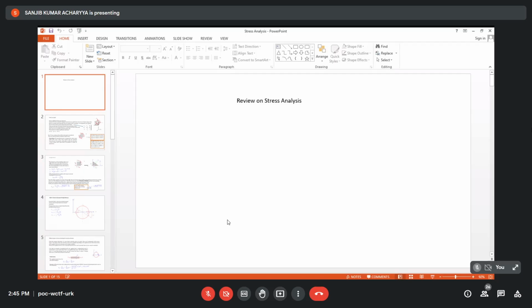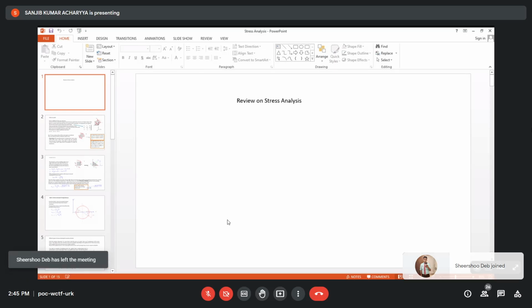And now this stress multiplied by the area will generate reaction force against the applied load. Until the generated reaction force counters or balances the applied load, deformation will continue. At the final stage of deformation, the stress developed multiplied by the area provided can counter the applied load.